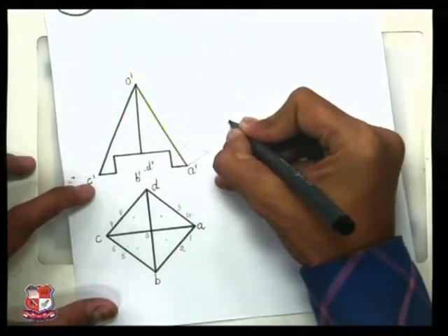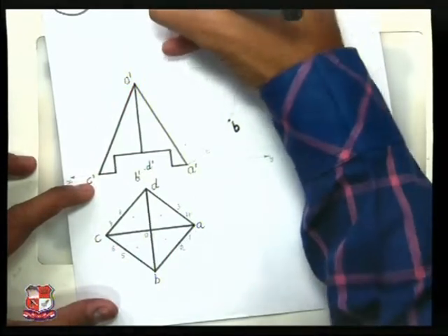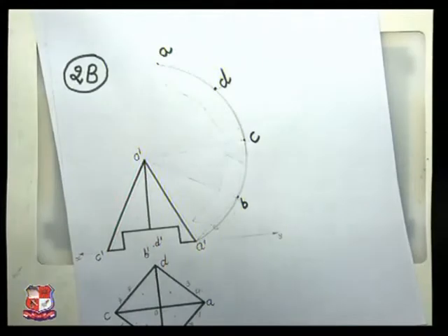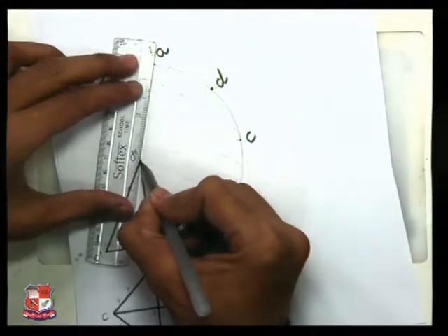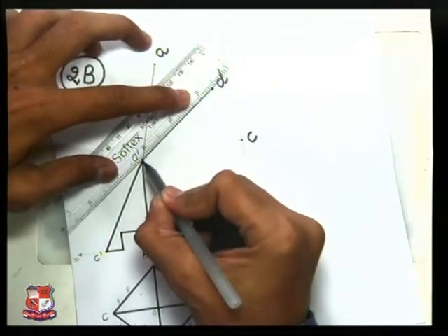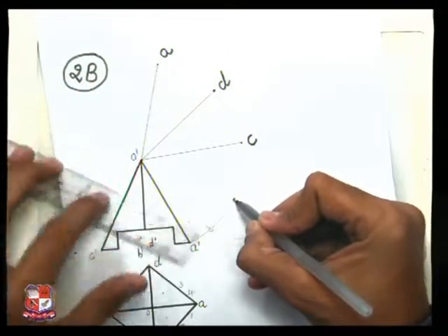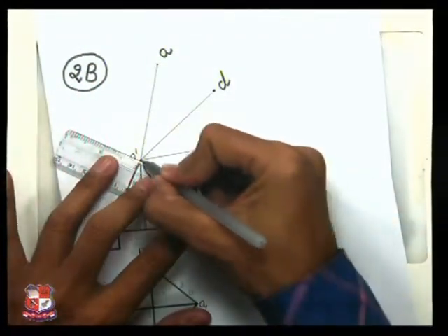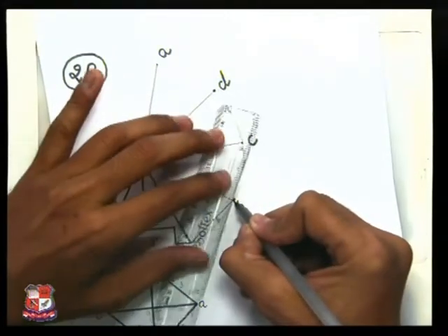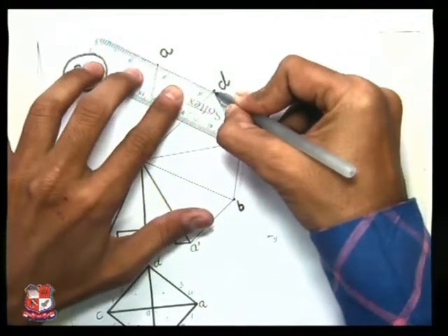A, here is point B, here is point C, point D and back to A, like this, and join all these points with a straight line such that we can form 4 triangles like this. So this shows the development of the square pyramid when it is not cut anywhere, like this. So 4 triangles would appear, all joined with the slant edges.